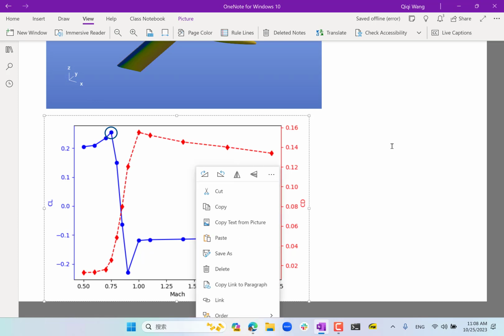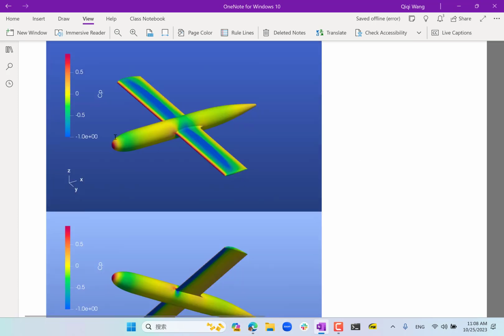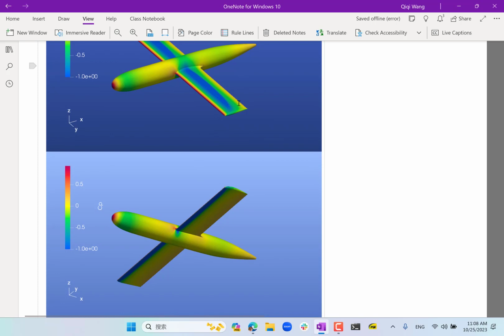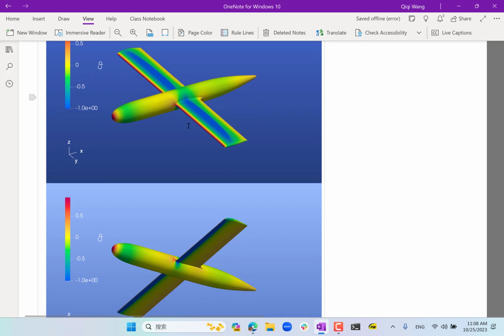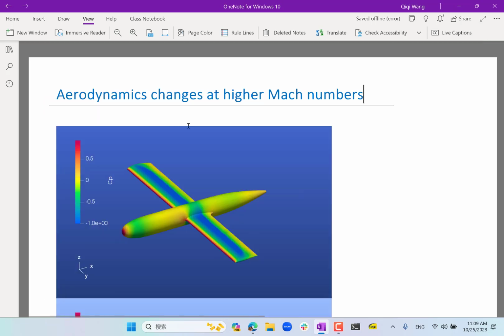This is at the peak of the lift coefficient. The Cp, the pressure coefficient on the upper side and lower side of the wing, looks like this. This is not qualitatively different from an incompressible flow. On top of the wing, you have a suction region. If you run XFOIL, you expect to see a Cp like that, since that's a highly cambered wing. And if you think about thin airfoil theory, you also expect qualitatively a pressure distribution like that.